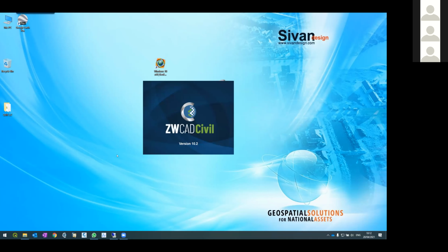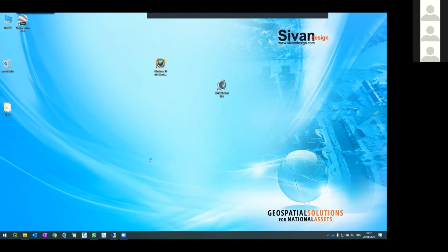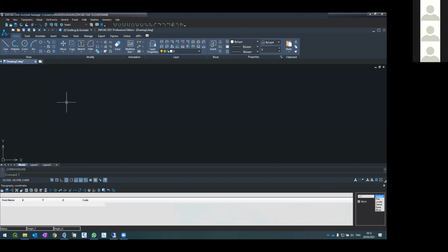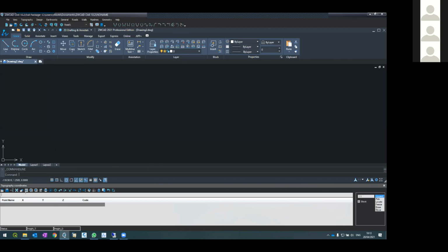settings. We talked about global scale, for example, the type of ZWCAD which you are launching, and so on and so forth. So this was the first training. We talked about the coordinates list here below and how to interact between this list and the drawing and vice versa. We talked about working with blocks. We talked about loading a file from Excel, showing the points, and then we ended the first lesson by creating contour lines. I hope you remember, this was the first training that we did.